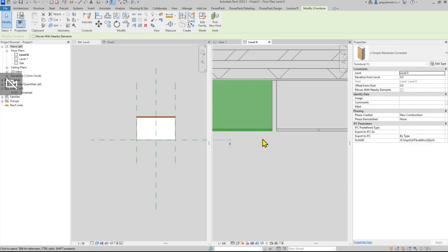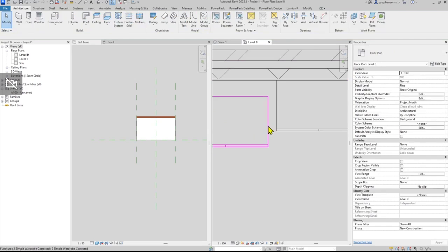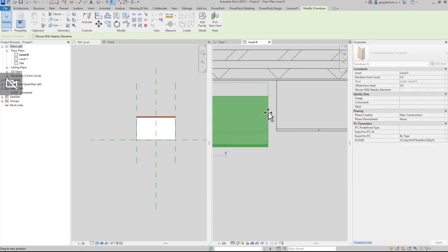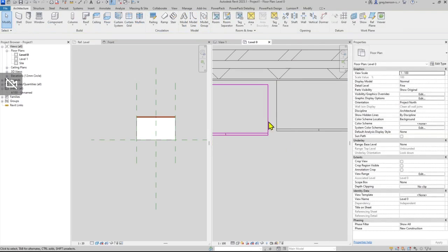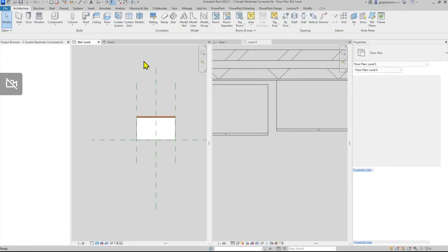And if this particular cupboard had walls to it internally, there'd be reference planes on the inside, and you could actually snap to those. So how can you make this easily snappable? When I say easily snappable, consider when I bring this to the wall, you get a highlighted line. It snaps. It's very obvious. So how do we make this happen for our sides? So here we are back in the family.